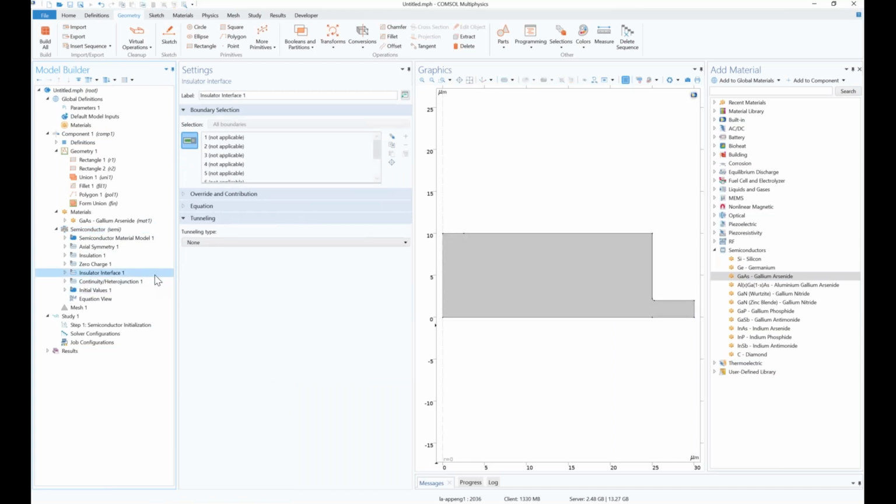Okay, so as the insulator interface, if you have those interior interface between the electric material and semiconductor, you will see this insulator interface where you actually can define some FN tunneling. Today, I will not put too much effort here, but definitely FN tunneling is usually coupled with floating gate. You can see an example in our library. Find that EEPROM example and see how to use it.